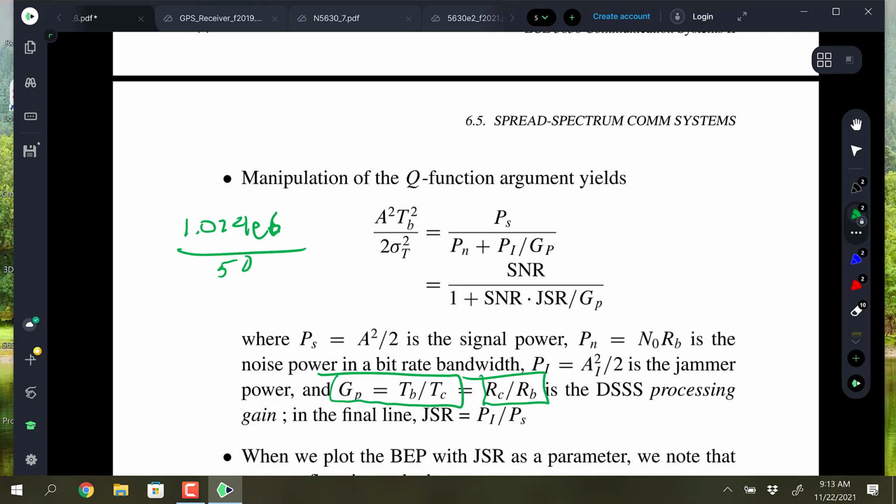Everything, though, costs the jammer something because they have to have resources to do that, whereas the CW is pretty minimal, and the CW is where it's the most effective to do spread spectrum. CW can hit a narrowband signal hard and decisively. I mean, it can wipe it out. And unintentional jamming is what we also talk about too, right? That's why we have frequency hop systems for Bluetooth and GSM, because it wasn't an intentional jamming, it just was happening. So frequency hop worked pretty good for that.